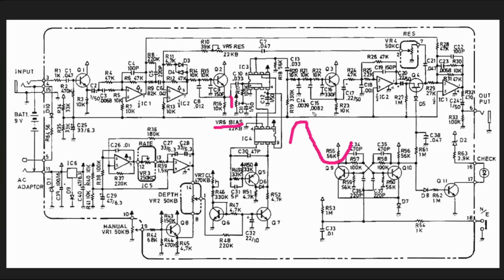Okay? If we were to just put a static resistor in there, because of component tolerances and everything, we might have it biased wrong so that our signal looks super clipped here, and then a big long full extension to the negative voltage, or it could look like we have our upside looks really great, but then our bottom side gets totally clipped off.